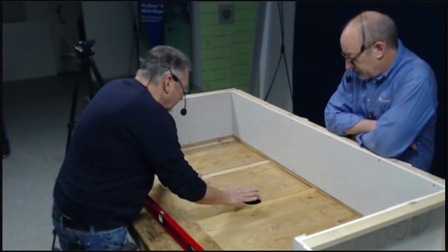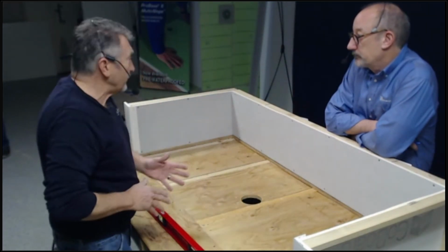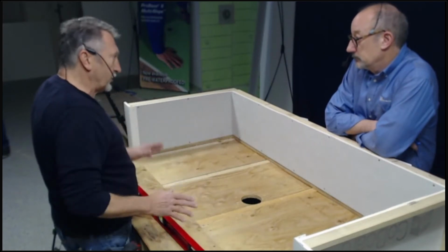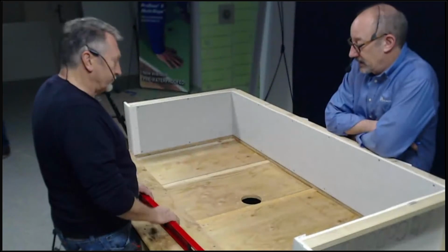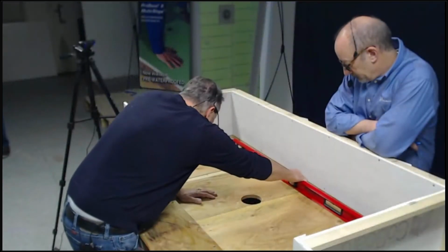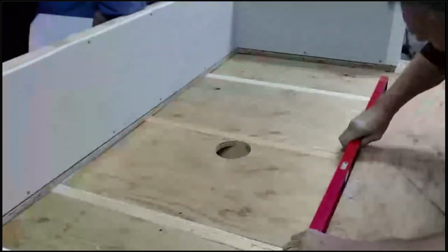Now, sometimes your floor joists may have a hump in them, or a sag, and you may have to sister something alongside of it, or plane that floor joist down to make sure that you have a nice flat surface. Flat's got to be important with a pre-made base. And level. Yep. We just want to confirm, go take a straight edge across it, make sure that everything looks good, and we're good.